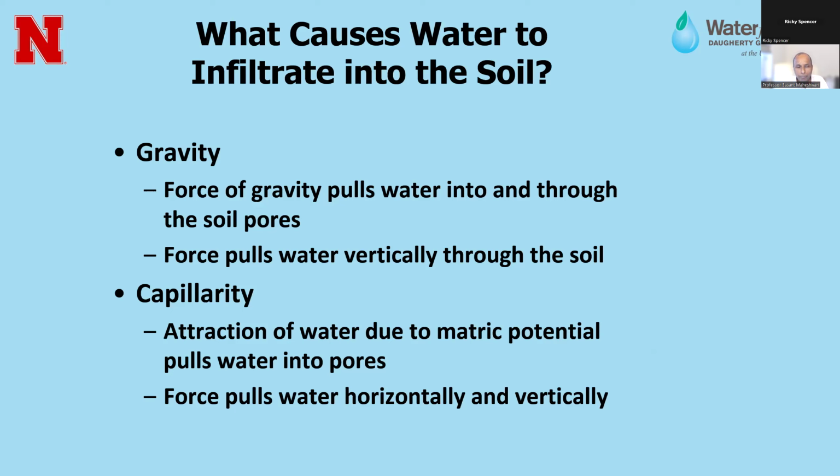So when the water is there, because of this capillary action, the water is pulled. When water enters through gravity, the capillary forces act on water and pull and distribute water within the soil profile horizontally and vertically. When soil is dry, the capillary force is at its maximum. Then when the capillaries get filled up, the capillary force decreases. And when the capillaries are full of water, that is, the soil is fully saturated, the capillary force becomes negligible.